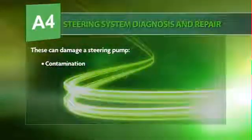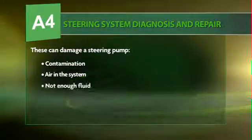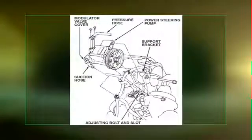While we're on the subject of pump damage, lots of things can damage the pump. Contamination, of course, air in the system, not enough fluid. There's a pump. We see there's our pressure hose, and there is our suction hose, and we would want to cover the hoses up, plug them up when we remove the pump. Obviously, remove the belt, support the unit.